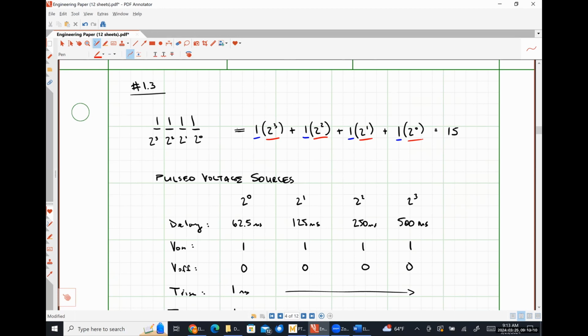So we're going to use a weighted inverting summer. And then the second stage, and we'll talk about that more in class on Wednesday, is just going to be something that converts that negative number that we're going to get out, because our weighted inverting summer gives us a negative voltage signal. The second stage is just going to invert that inverted output to give us a positive number.